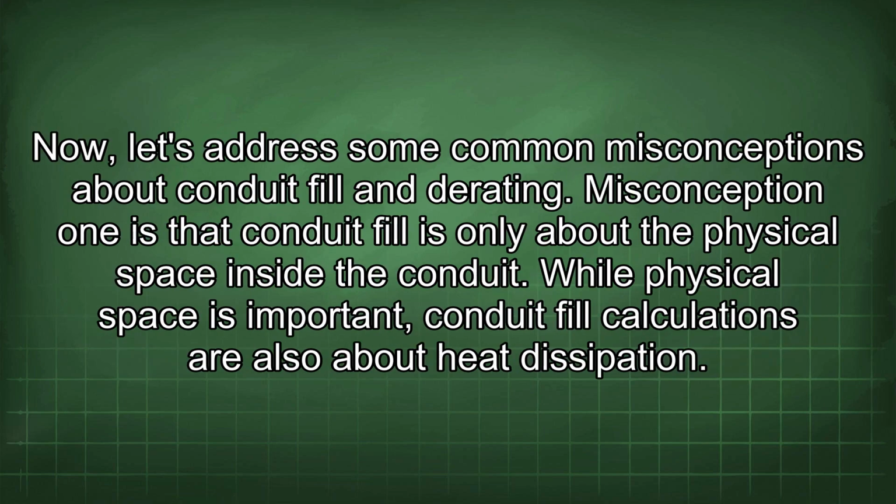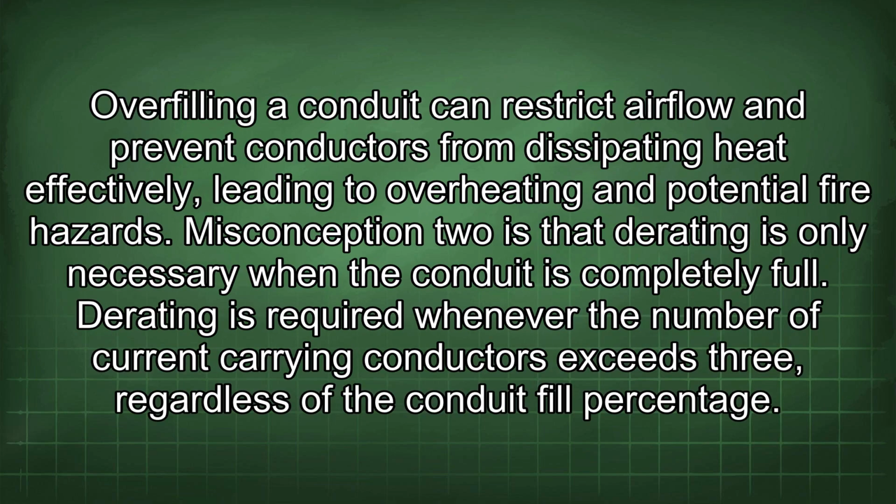Now let's address some common misconceptions about conduit fill and derating. Misconception 1 is that conduit fill is only about the physical space inside the conduit. While physical space is important, conduit fill calculations are also about heat dissipation. Overfilling a conduit can restrict airflow and prevent conductors from dissipating heat effectively, leading to overheating and potential fire hazards.